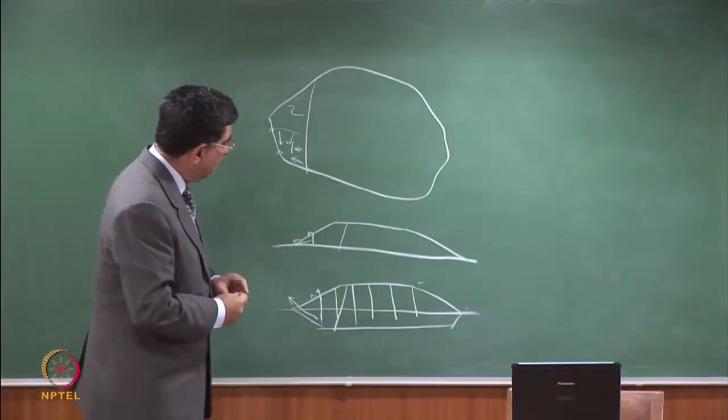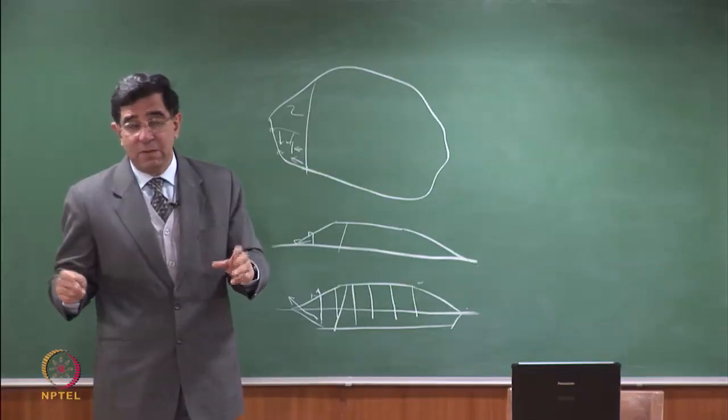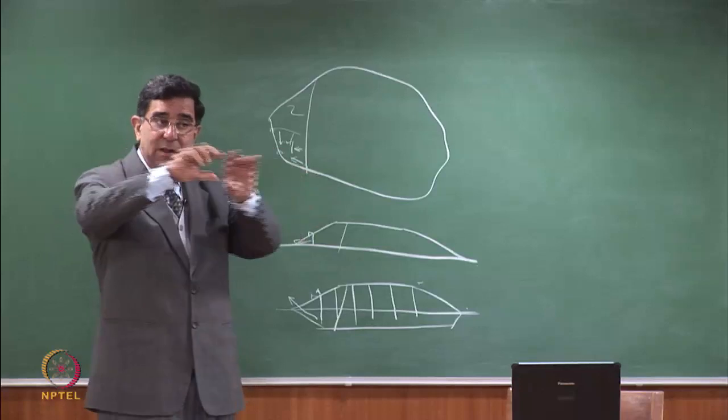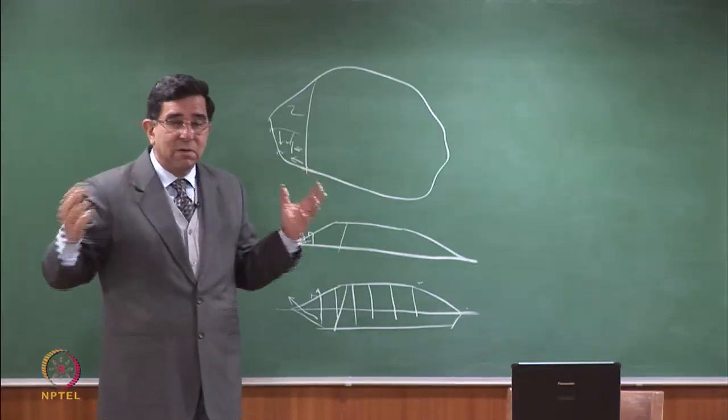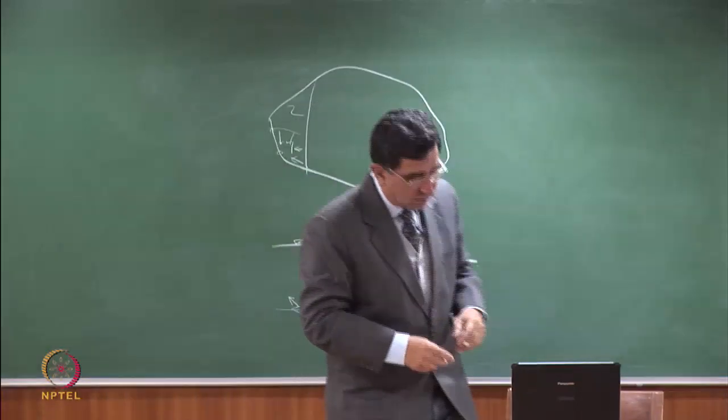So the starting phases which are on the sides may not have many wells. You may have a gas collection perimeter trench. You will have the gas collection layer under the cover. They will work as gas collection. Wells may be used at slightly different locations.